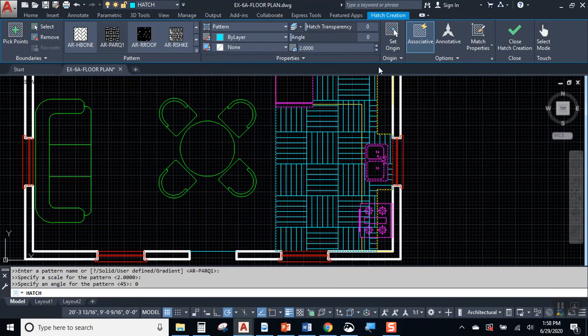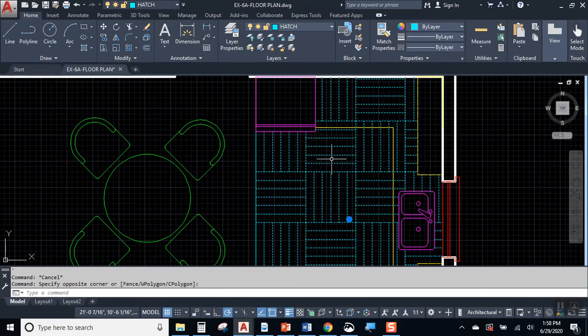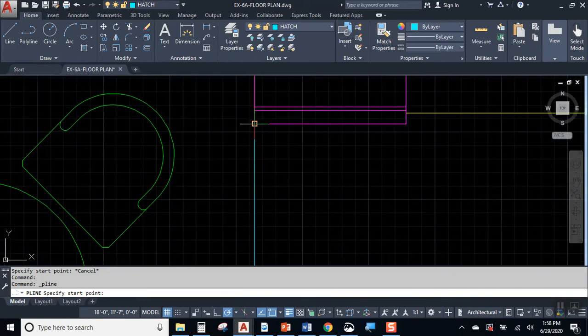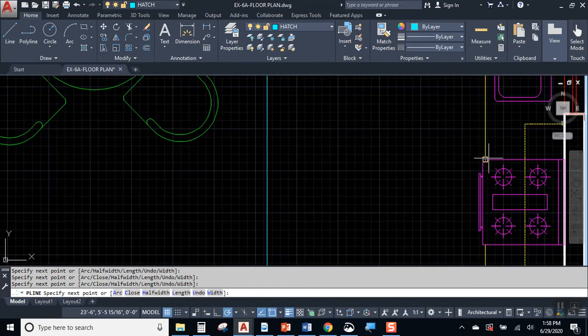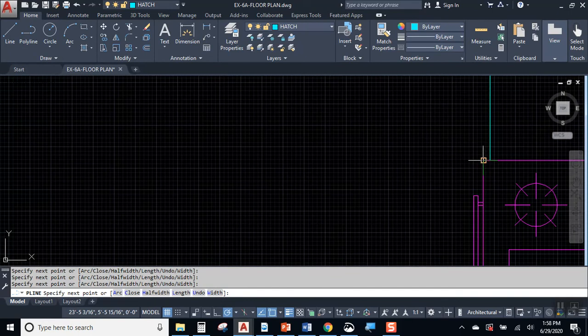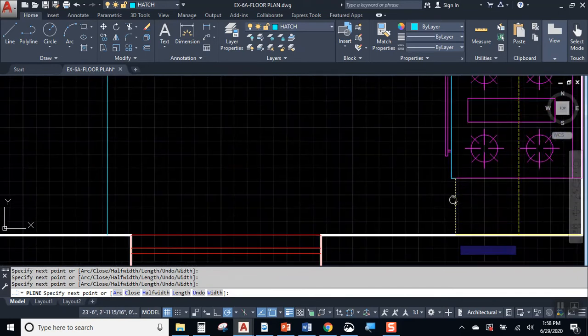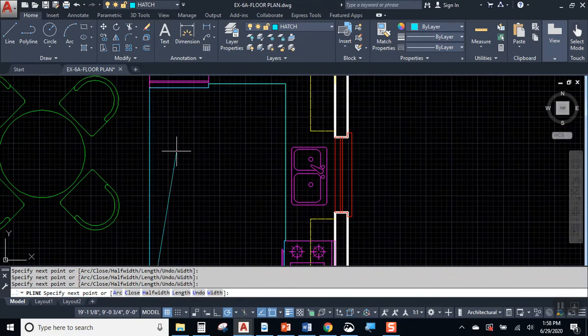I'm not really liking the fact that it's spilling into the counter, though. So when that happens, I'm having a problem. The problem might be something simple. The problem might be something more complicated than I'm planning on working with. What I'll do is I'll just go around. I'll draw a boundary so that AutoCAD knows where to stop. Because, you know, sometimes it just doesn't know where to stop. And Hatch, while it's so simple, can be really frustrating. And then I will close the polyline.